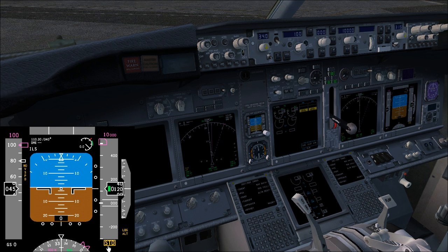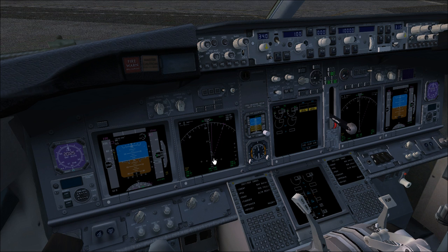Standard is now in yellow because we have not yet passed the transition altitude that is expected by the FMS. You can select the transition altitude in the FMS, and when you pass the transition altitude, it will go to standard in yellow. You press the standard button, and the standard indication will be in green. Reselecting standard will go back to the normal indication for barometric pressure. Now we will go back to 1013, which is my altitude setting at the airport of 1012, and this is okay. Then we have the controls for the navigation display.